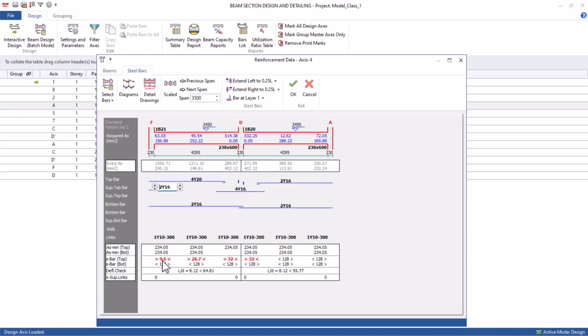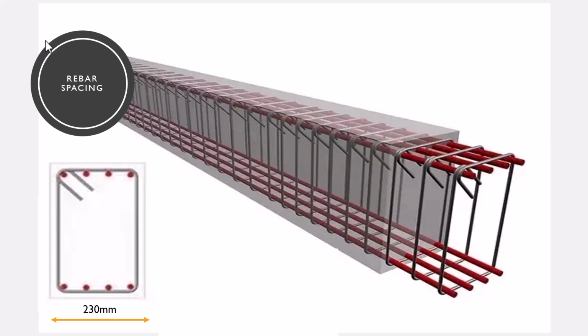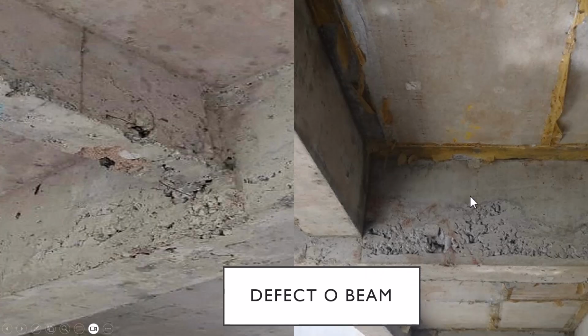So you must always look at this, because this can make honeycomb straight inside your beam, and that means you will have something like this. If there was not enough space between the rebar for it to receive the concrete, you see inside there will be some honeycomb inside the concrete. So this will also make you recommend, because there are cases maybe you have to stick with a smaller size. You have to make a recommendation that this beam at this very floor or this very level, ensure this is the coarse aggregate size that you will maintain for us to maintain this level of rebar arrangement.